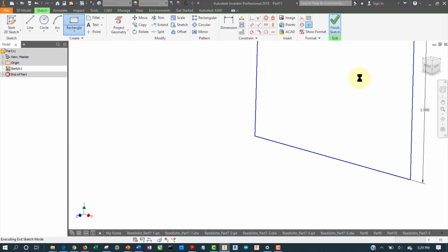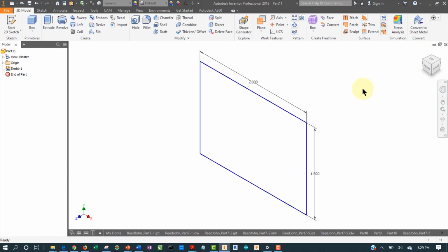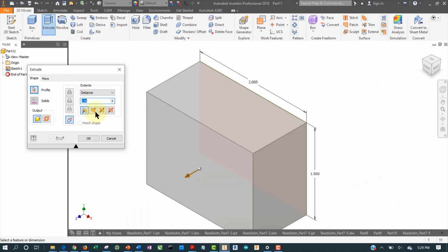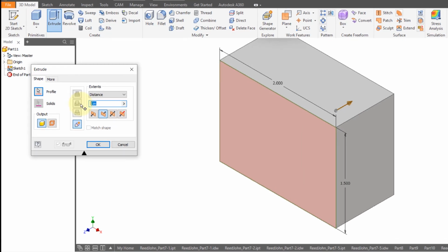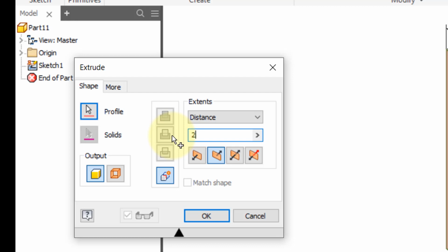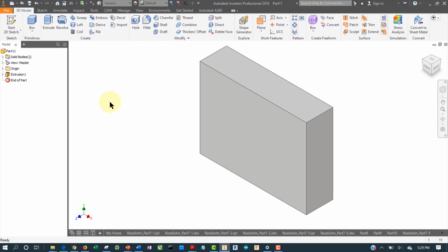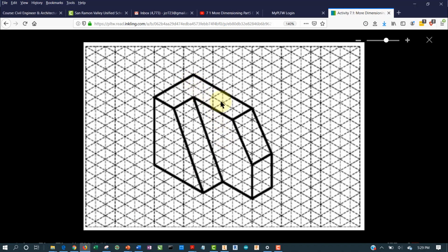And so I'm going to finish that sketch, hit the house, get it into view, extrude. I'm going to go into the page, and I'm going to go here 2 times 0.25. So what I've done here is I've made this area back here that's 2 units deep, and I'm going to cut out this little chunk here, and then later I'm going to add this part up front.